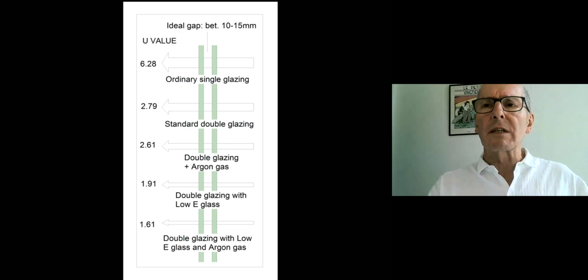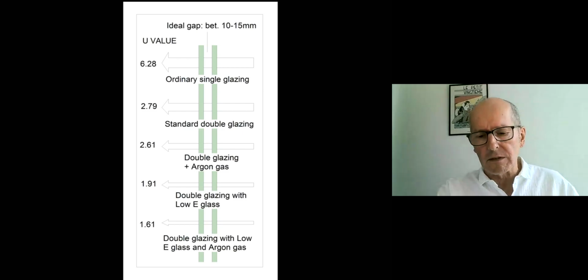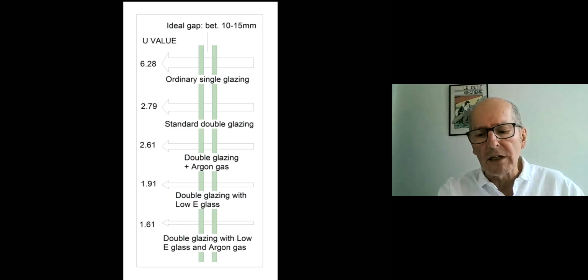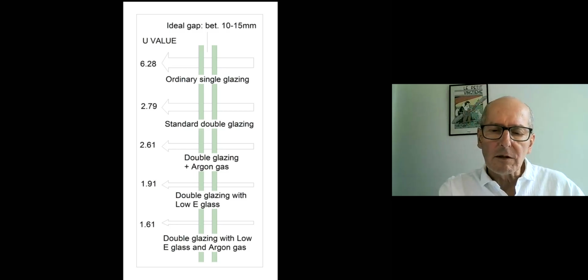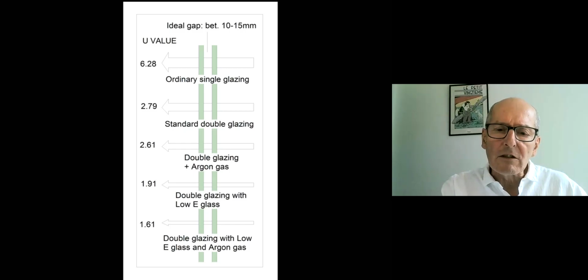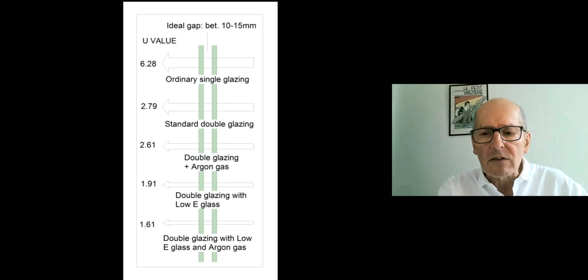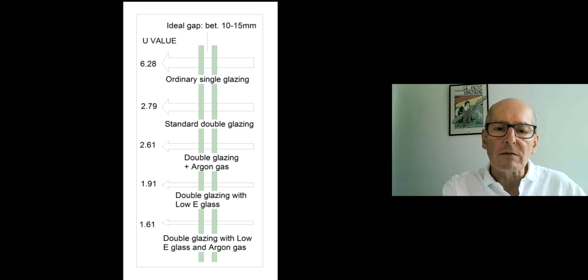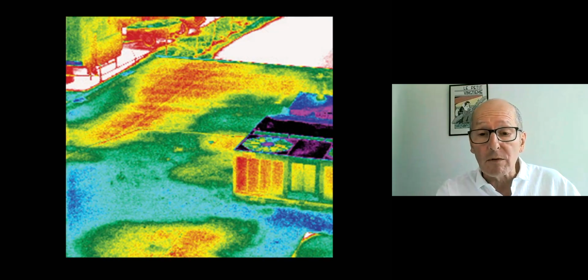But of course, if you're really doing the whole life audit of a building, a complete audit of the energy a building uses, from the embodied energy through to the operational energy, you think about the manufacturing and delivering to site of a triple glazed section of glass. Glass is a very heavy material. The embodied energy in glazing a building in that way, against the amount of heat loss that it's going to mitigate through its lifetime, is a complicated calculation to make. I'm not always convinced that you might not go back to that single pane of glass. But again, knowing where the sun is is important.